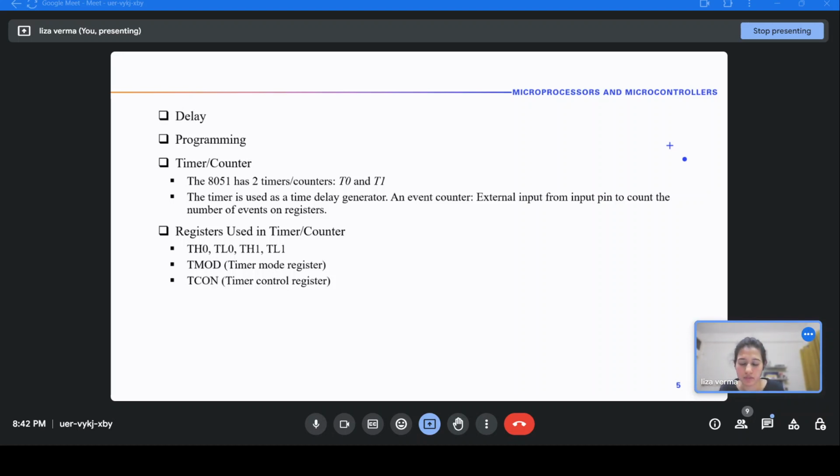Initially TLX contained some value, and it has the same value again. So the signal for timer overflow is fed to THX also. Understood. That is mode 2.